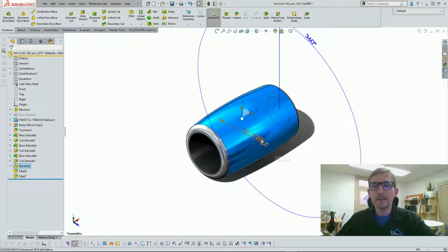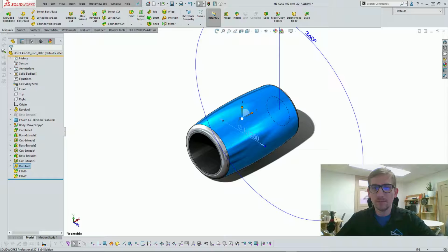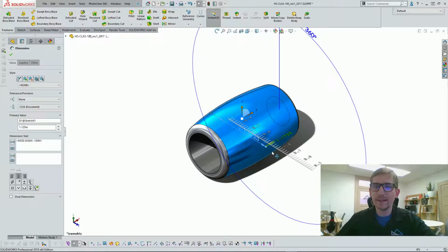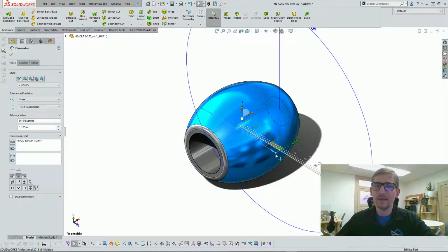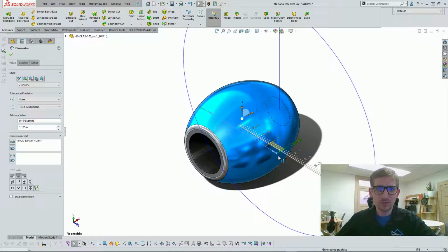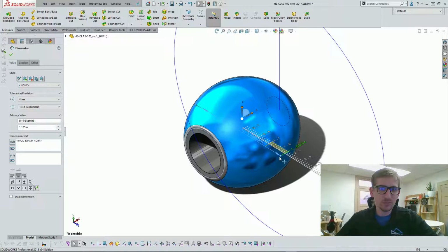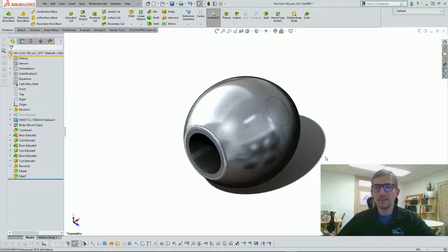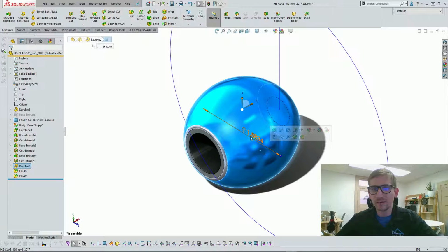You'll see here on the end of my 1 1/8 dimension that I have this blue dot on the end. What I can do with this is actually click and start dragging it out. Now, as I was stating, when you're doing this drag function, wherever you send it out and let go is the dimension that's going to show up. It's a dynamic change. By that little drag and drop that I did there, that dimension ended up being 1.8834. It's not a very friendly dimension if you send it off to a standard machine shop, right?